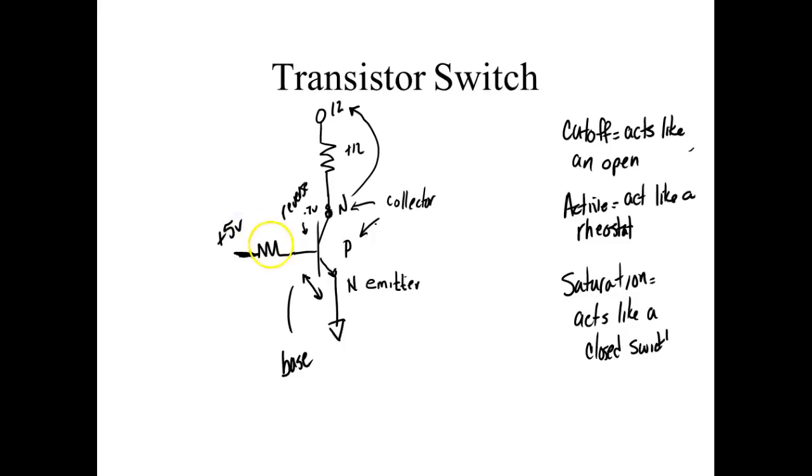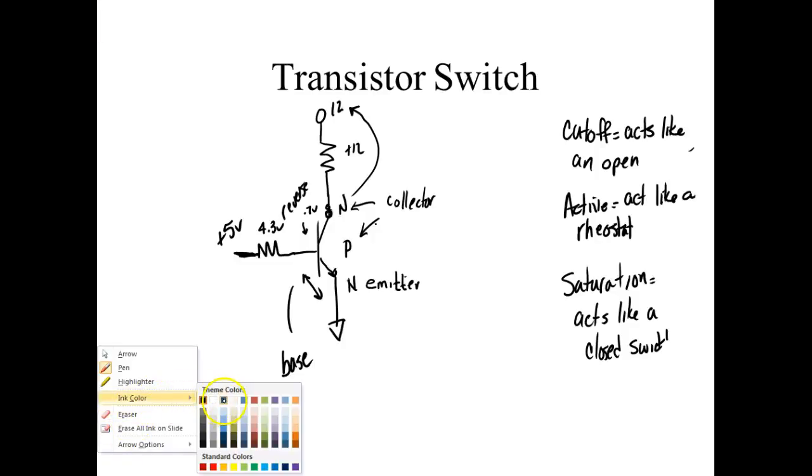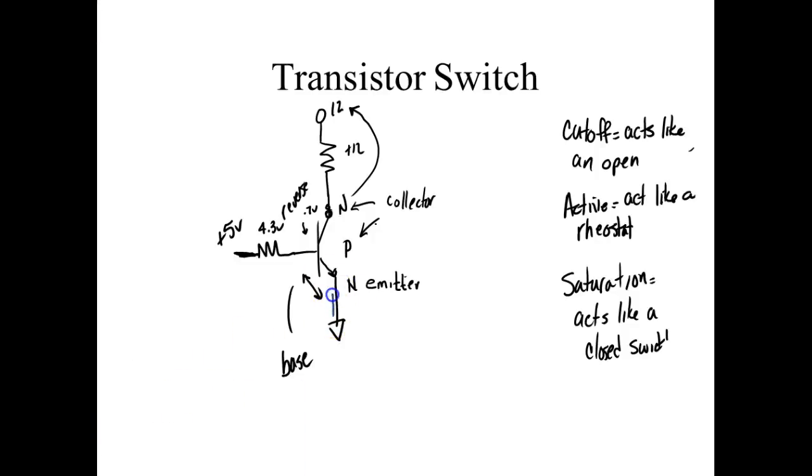Well, that means I'm going to have to size a resistor to drop 4.3 volts, because Kirchhoff's law says the sum of the voltage drops in a loop has to equal the applied. This makes sense so far? So if I put plus 5 on there, that creates a circuit, and then we come up here and generate a path through here.